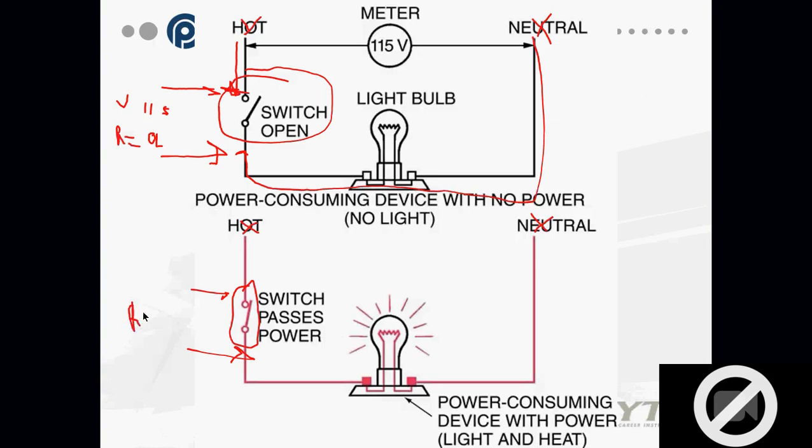Okay, resistance across a closed switch. Damn, I'm slow. Have another cup of coffee. Resistance across closed switch. Is the power on or off? Off. Anytime we put an ohm meter on here, we have to shut the power off. Oh yeah, it should be 0. So resistance across a closed switch is always 0.